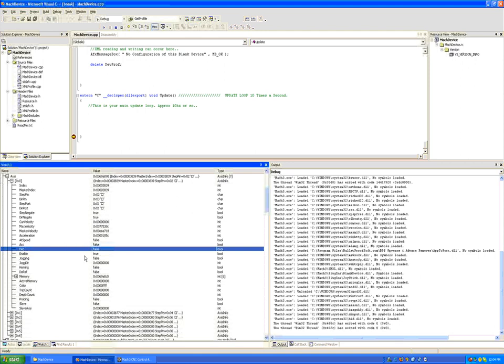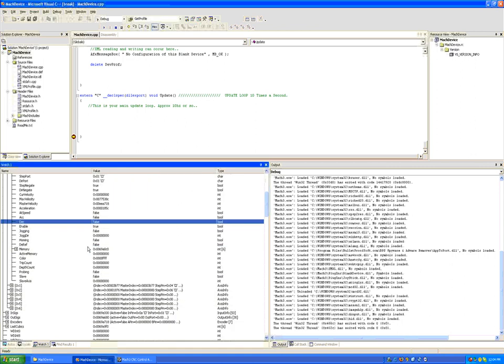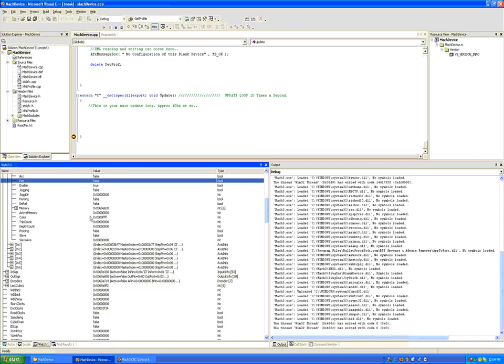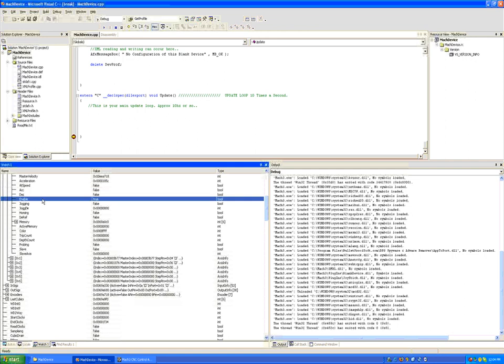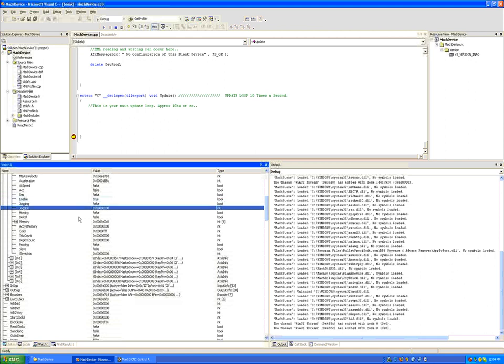You don't even try to follow these explanations, by the way. I'm simply giving you examples of what they do. You're going to have to play with a lot of them to see. Enable tells us if an axis is turned on or off. You could disable an axis, for example, just by setting engine axis, whichever axis, .enable to false. We have a jogging variable telling us whether the axis is jogging at the moment, and a jog direction that it is jogging.